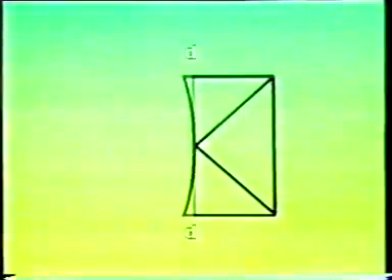A K bracing is a statically determinate truss able to resist forces in both directions. The diagonals are loaded in tension as well as in compression, so the bracing level is of minor importance. The cross girder has to follow the deformations by bending with respect to the weak axis. As an axially loaded member is more rigid than if loaded in bending, the deflection D is completely accounted for by bending of the cross girder.